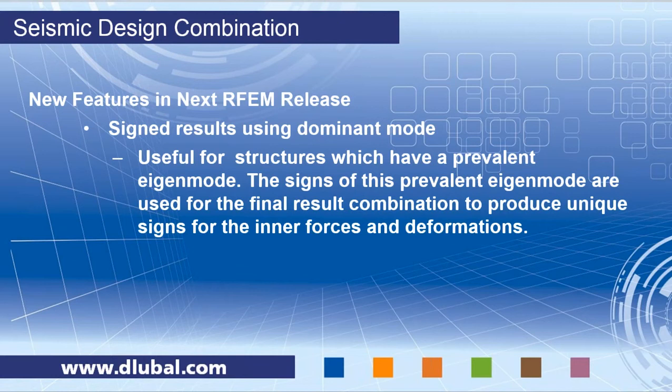You can use the SRSS rule or the CQC rule, and if you use it, you have the option to use the signs of the prevalent eigenmode and take these signs for the whole result. That means you don't get two signs for each result combination.